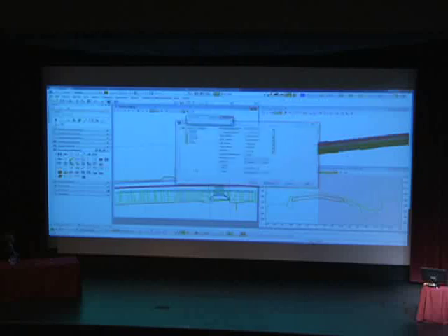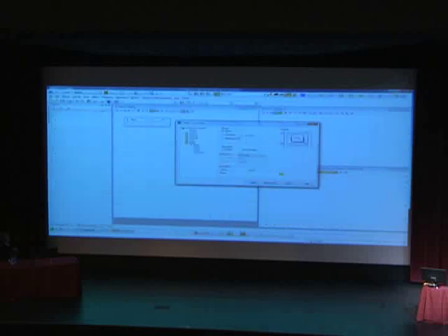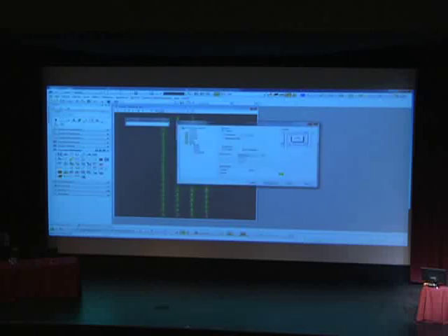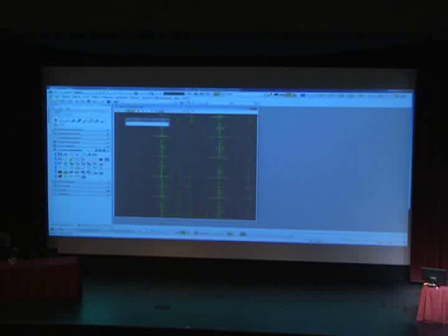Next, what I want to show you is just cross sections in general. So guys, we can still create our green cell cross sections. Those green cell cross sections, we can still run our old tools off of that too, for example HEC-RAS or whatever we have to do. What I did was I selected preferences, and I just put stacked 10-foot cross sections. Then I selected the model name that I wanted to create it under. And I put a vertical exaggeration of 10 on there just so it looks a little bit neater. So you see, these are the cross sections we're all used to seeing with the green cell.